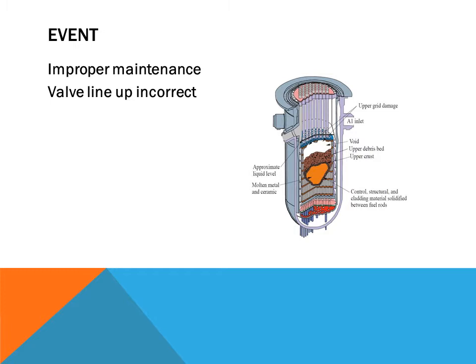This instrument air line that was incorrectly hooked up filled with water and slammed shut automatic valves due to the pressure. This pressure and the shutting of these automatic valves eventually led to the stoppage of main feed being flowed to the plant. So when the aux feed water pumps tried to start up, they started, but the valve, as we discussed, was shut. So you have zero flow to the steam generators.